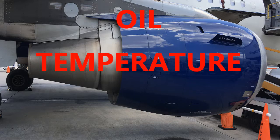Okay, and for the oil temperature indicating, only the oil temperature for the engine condition monitoring is indicated, not any other oil anywhere else. It's just the oil temperature for the engine condition that's going to show up on the ECAM through the FWCs, and also the DMC.